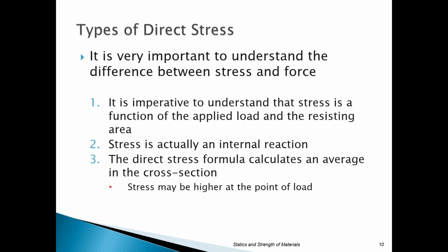So it's very, very important to understand the difference between stress and force. I'm going to emphasize this now and keep saying it throughout: stress is not a force, okay? It is an internal resistance to that force, all right? So it's an internal reaction, and to calculate it, it's just using that cross-section.